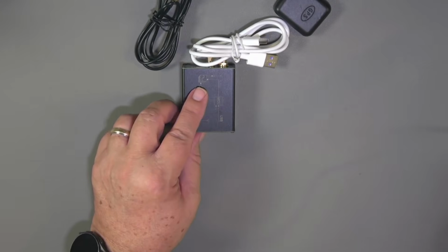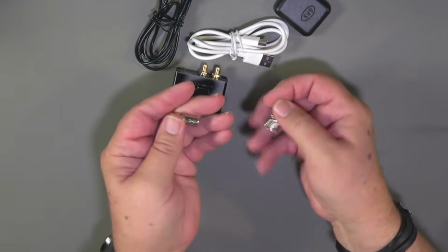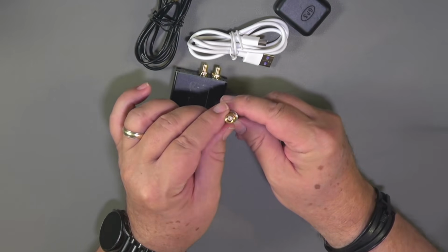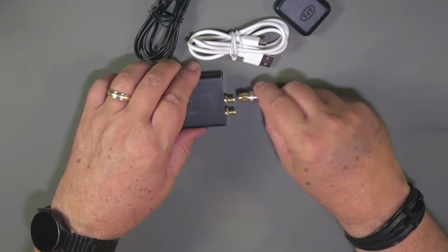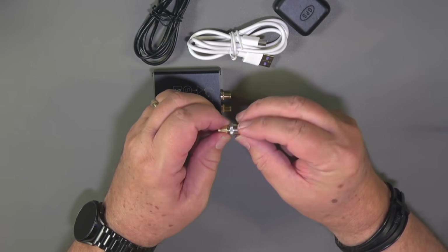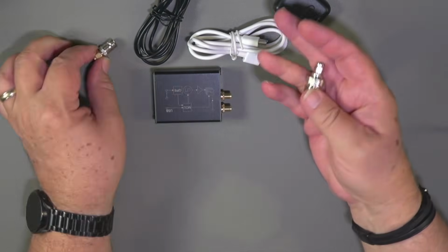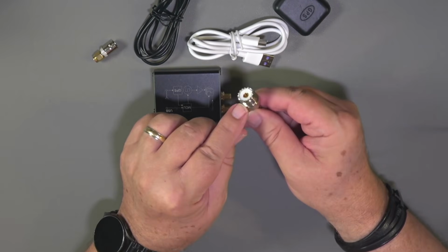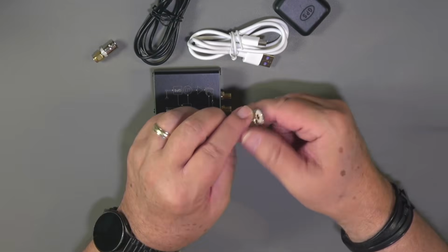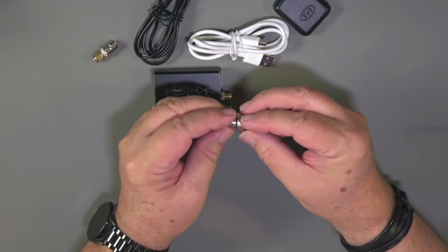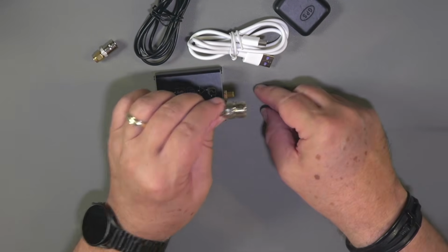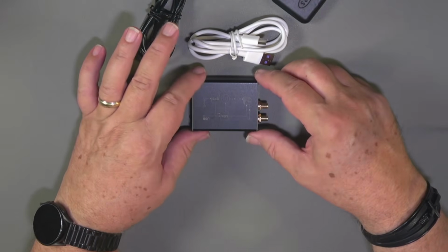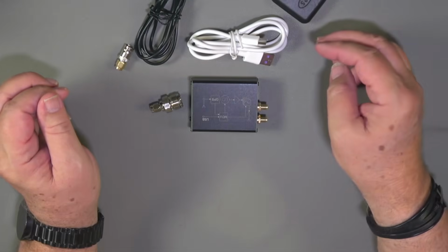There are two other things that you're probably going to want, and these are adapters. And so this one is a BNC to SMA adapter. And so it would fit here on the antenna side. And then you can connect your antenna if it has a BNC connector on it, or you can get one like this, which is the same SMA male here, but it's on an SO239. So you can connect your larger coax that have UHF connectors here on this. And so that's the primary parts you're going to need, one or the other of these, depending upon what kind of a coax you're going to bring it in on.